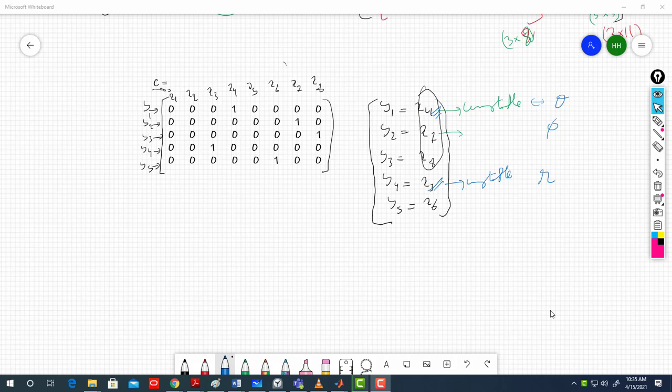So now we did two examples, actually two big examples on MIMO system, and we saw it is similar to the analysis we did in SISO system in the lecture. Just you need to pay attention to your dimensions. And also we learned that we can do it on control system tuner app without using place. And control system tuner app is using an iteration way, an optimal control way, in order to reach the goal.